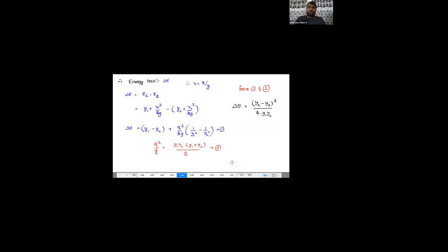See, this is delta E, and I'm not doing the total derivation. We don't require the total derivation. So you just substitute this Q square by G as this value. If you do so, then you are going to end up with the delta E value as Y2 minus Y1 whole cube by 4 times Y1 into Y2.